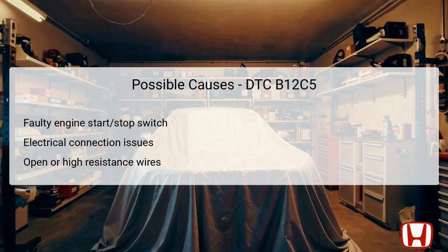The first potential cause to consider is a faulty engine start/stop switch, which can happen due to wear or internal failure. Following this, it is critical to examine electrical connections for issues such as poor connectivity, frayed wires, or deposits that could impede electrical flow.